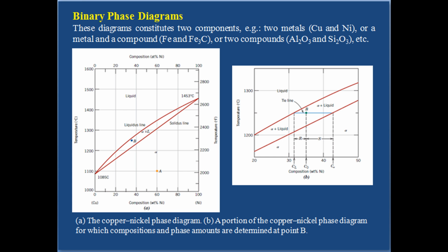Heating pure copper corresponds to moving vertically up the left-hand temperature axis. Copper remains solid until its melting temperature is reached. The solid to liquid transformation takes place at the melting temperature, and no further heating is possible until this transformation has been completed. For any composition other than pure components, this melting phenomenon occurs over the range of temperatures between the solidus and liquidus lines.